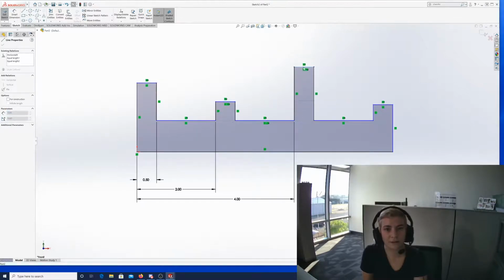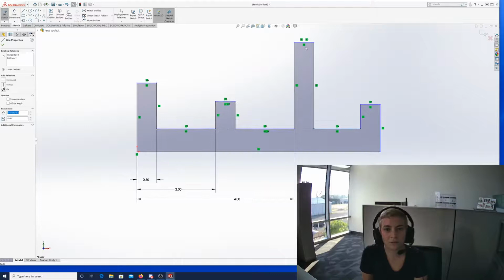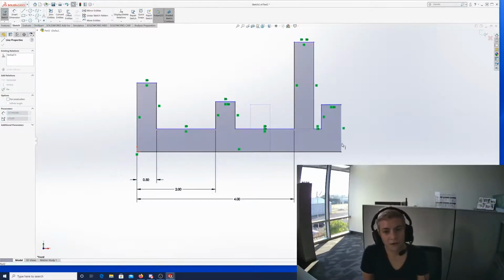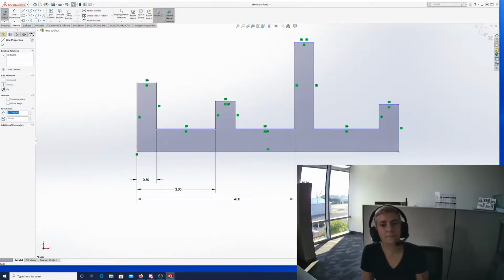but I can change the heights of my towers. So basically you can grab a line that's blue and you can move it around. I can even change this if I want to. But if you end up with everything overlapping like this, just identify what needs to move. So if you look at the bottom of your drawing, you'll see this line here. You know that that needs to be longer because one of your towers is way out here and it shouldn't be. So grab this part of the drawing right here, what you know is supposed to be your last line, and just drag that out until it's not overlapping. Does that kind of make sense?